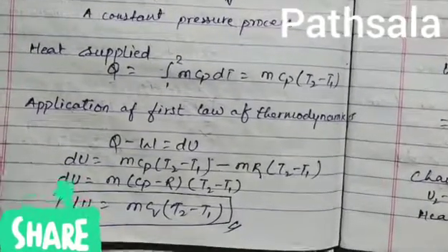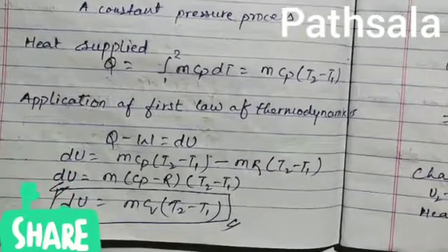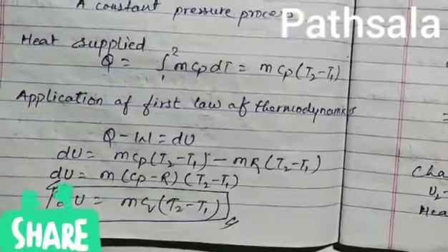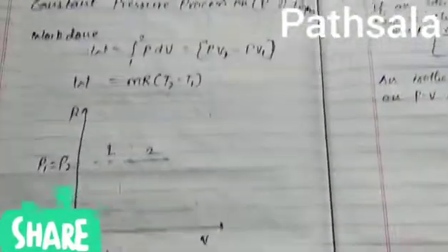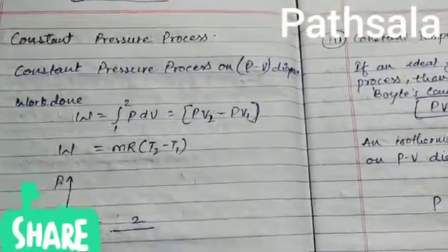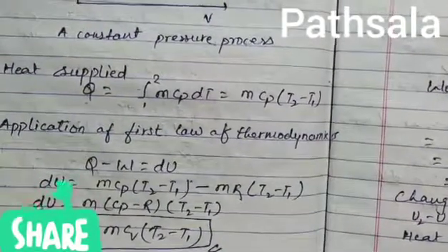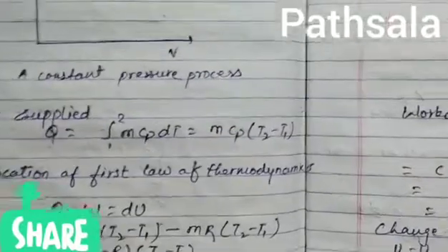Here m and T2 minus T1 are common, so we get Cp minus R. As you can see, Cp minus R is equal to Cv, so dU is equal to m Cv (T2 minus T1).